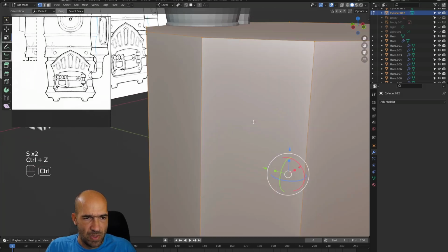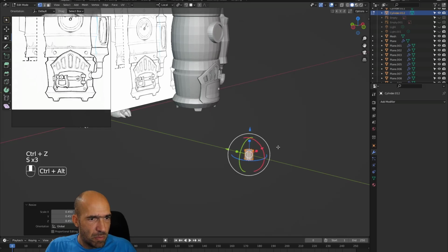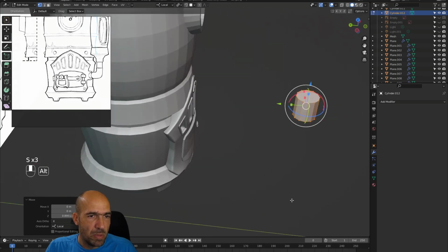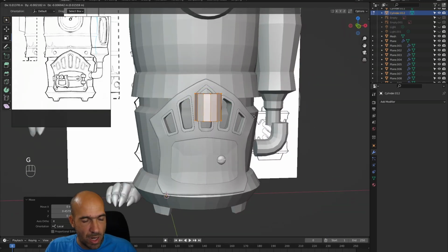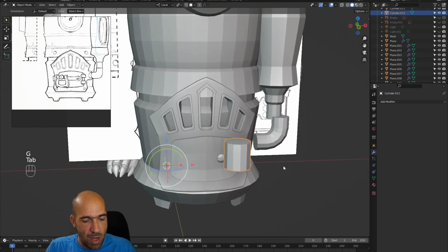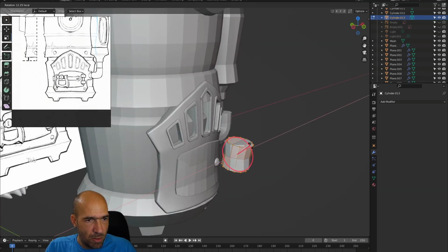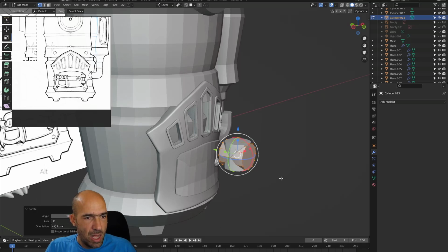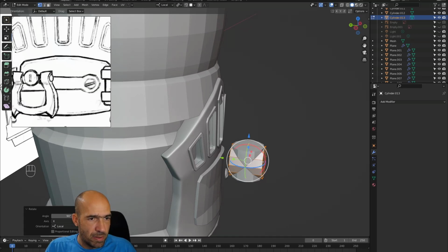Now it's turned. I will Control Z and try to move it in small increments, because otherwise I have to flip it, which is not a big deal. I will flip it, but I don't like to flip it. But I have to sometimes. Okay, now G here. Then I will press Shift D to make another object. And this object, I will go and rotate it 90 degrees. Just behind me, I will press 90. And this will be this thing here, you will see.